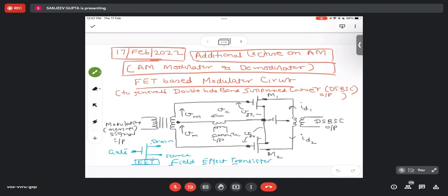So we thought of having a double sideband suppressed carrier. That means you will get only the two sidebands, the lower sideband and the upper sideband. And then we have talked about the single sideband also. Because the same information is contained in both the sidebands, why have two sidebands? We can suppress one of them also. So I'll get a single sideband. Let's understand how we do this.